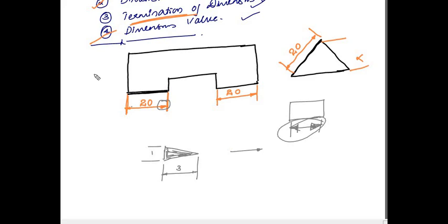And you need not measure 1:3 every time, but generally by practice you get that. The standard is that the height should be 1 mm or 1 unit, and the length of the arrowhead should be 3 units.